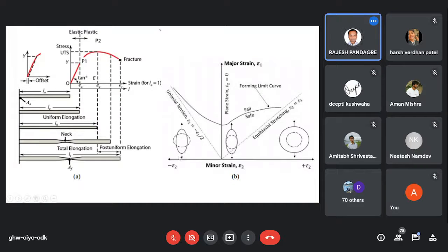In the etching, which is the physical thing, we understood how the material is flowing. We can see that physically on the draw panel. But in the virtual case, this shape is already built into the software. So once we have punched the upper die onto the lower die with the blank between them, this parameter will show whether our die face is safe, and whether the desired shape is manufacturable or not.